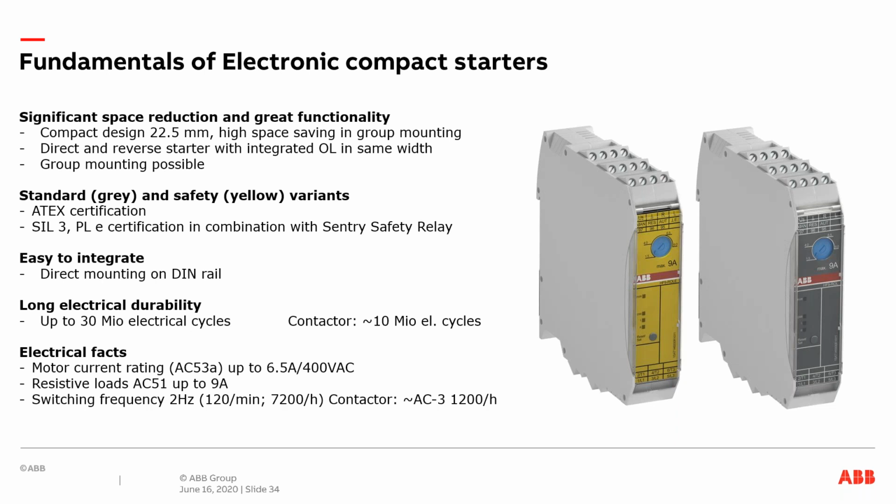It has integrated overload as well. It can be group mounted. It comes in ATEX certification, and we also have a variant for safety applications. You can get SIL 3 rating or PLe certification with Sentry relays. It is very easy to mount. I have wired this myself, and it's very easy to wire. You don't need any additional circuits. Everything is there, all the connections. You just have to pull some wires and give it to your push button or an indication.